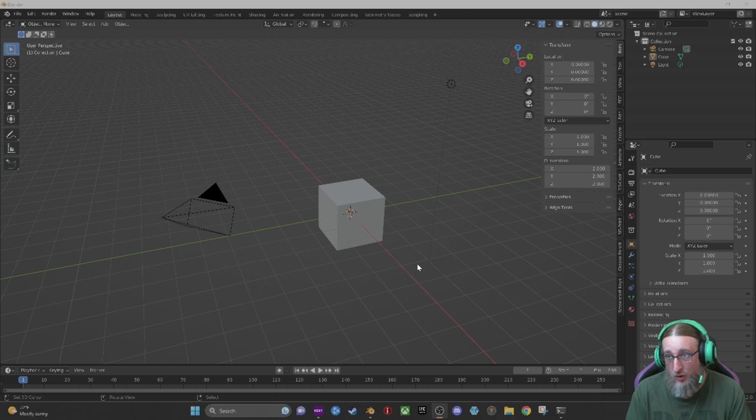But now we're going to add in the same image that we had from before. So we're going to click on Open and then find where we had that image set before. And you're going to see there's our image. And if you hit period on your number pad, that'll also center wherever you're looking. So just hit period on your number pad and it'll center where you're looking.